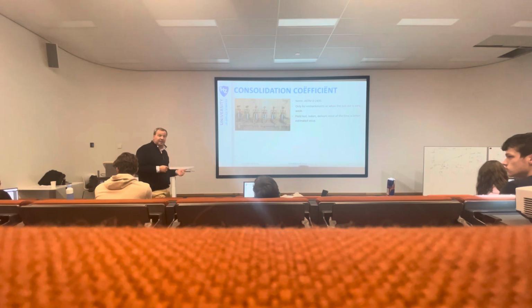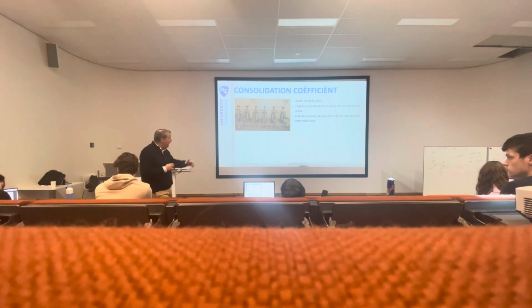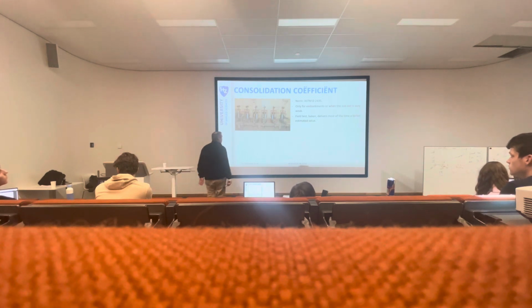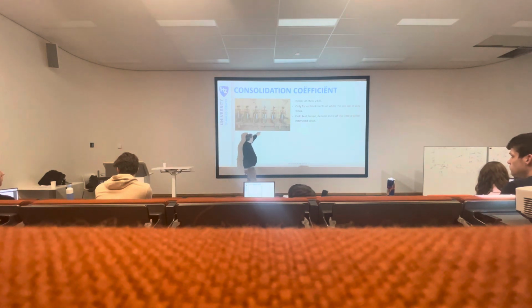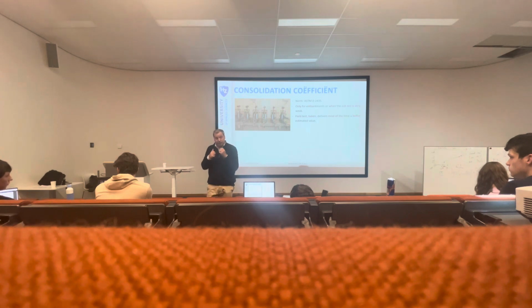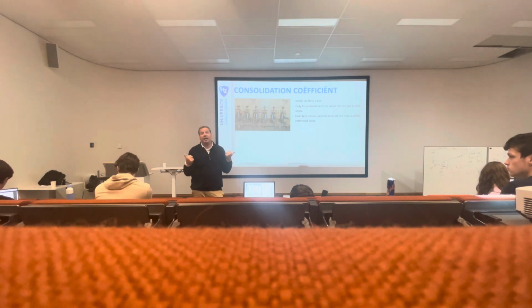Okay, so with this test we just check how long it would take for the water to get out from between the little plates of the clay particles. Yeah? That is what we test with this machine. We hang a certain amount of weight on it, so we can test, depending on the weight, whether we see a difference in the way the clay particle sinks. So that means how much does it go to the side.